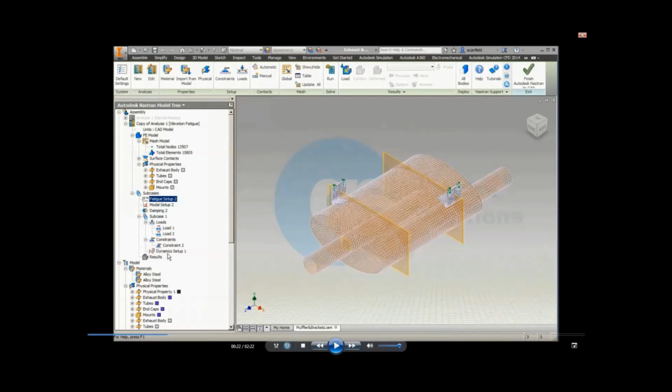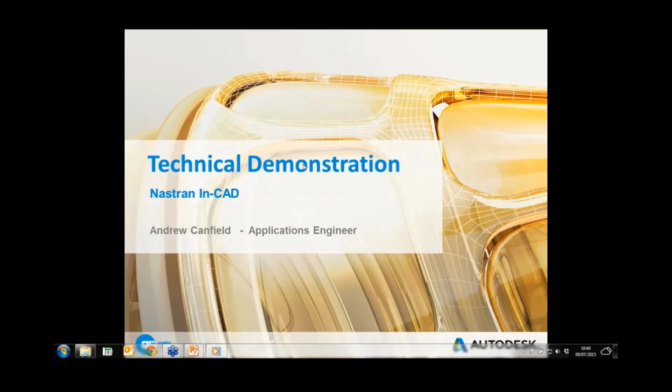It is quite memory and disk space intensive, so once it is calculating hundreds of thousands of points on the meshes and the nodes, and these analyses need saving. So if it is a large model, you are going to be creating a lot of data. So the bigger the disk drive you've got might help. Right, okay.